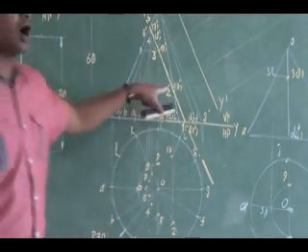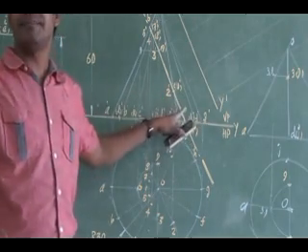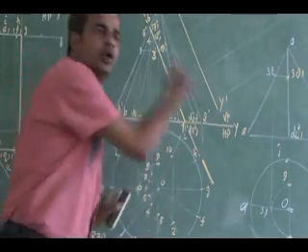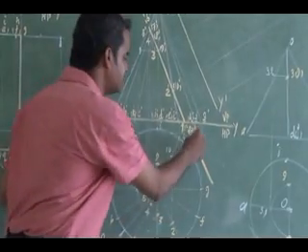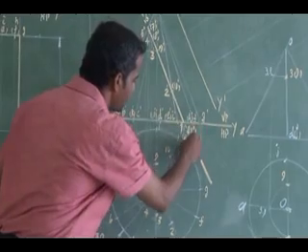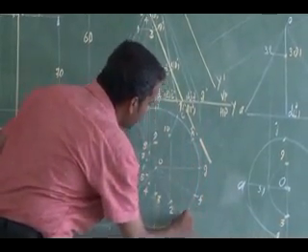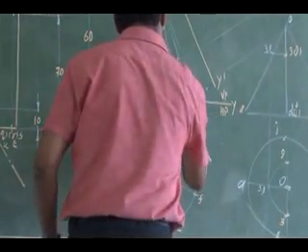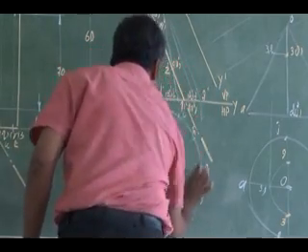Listen. Then all the generator cutting points have been transferred. What about the base cutting points? The base cutting points are 1 and 11. They should intersect the base circle. So just project the 1 and 11 cutting points, and wherever they meet this circle, that is my base cutting point.